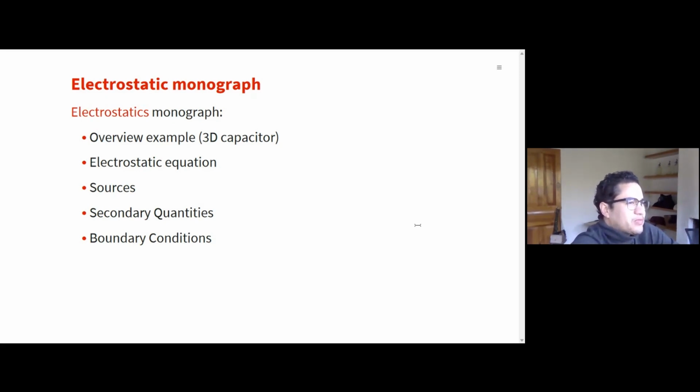This is really useful because you can compute electrostatic forces between electrodes and between dielectrics, to see how much force there is between these two objects. And we introduce how to compute these forces with a really general method, the Maxwell stress tensor. So it is really helpful to compute this kind of quantity.